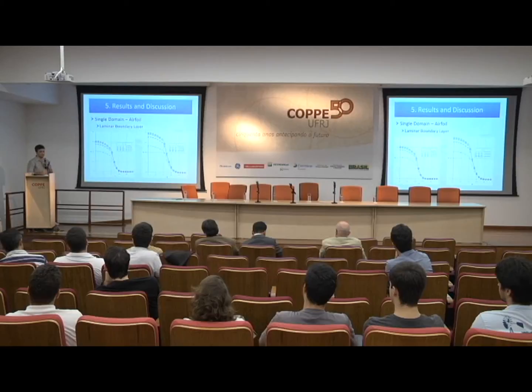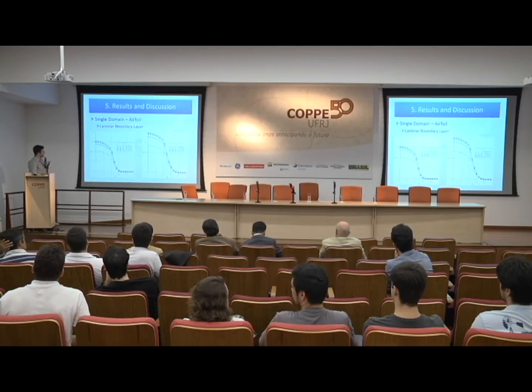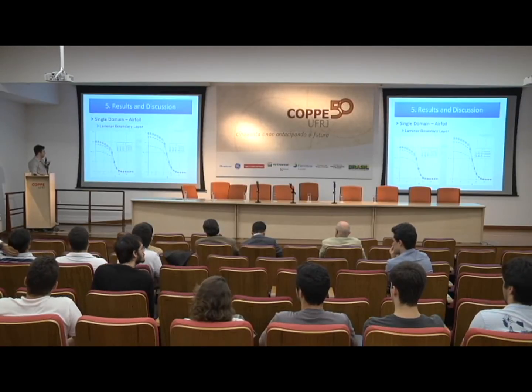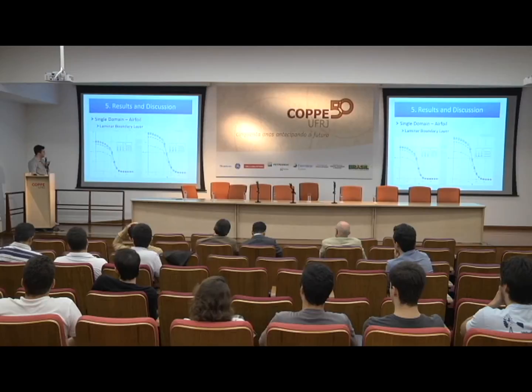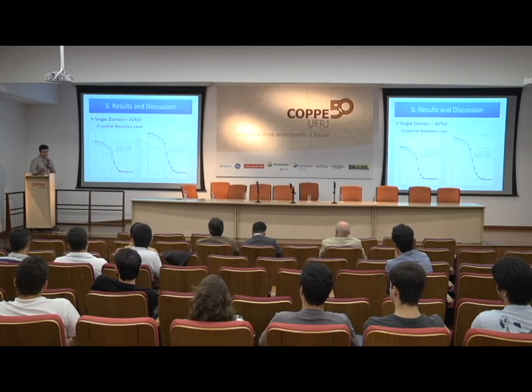And now for the airfoil, I have some basic results, just for showing that it works. I'm running some simulations now as we speak, basically with the wall with a constant heat generation. And here we have the transition to the fluid. We have the interface around here. And this is done all together in just one model, just one system to be solved.